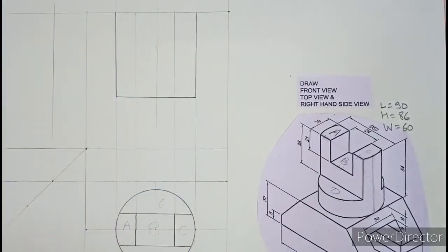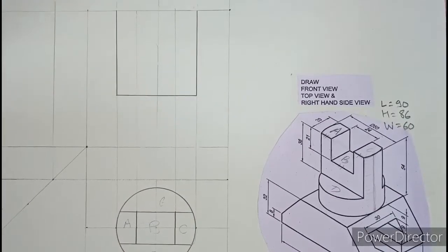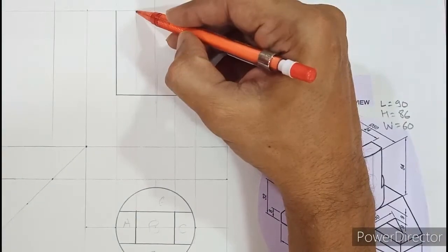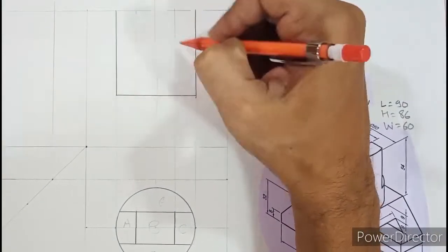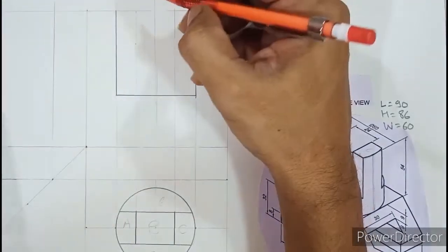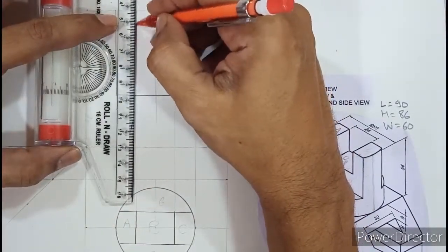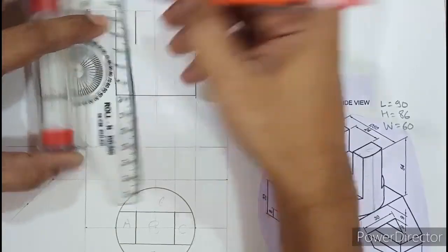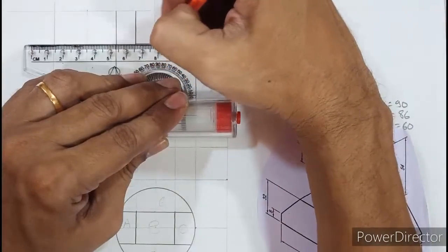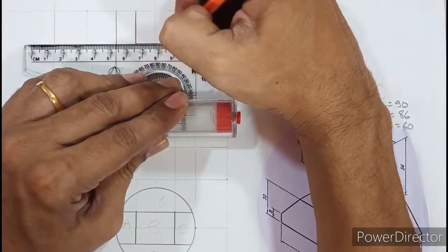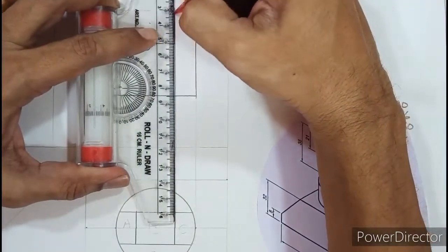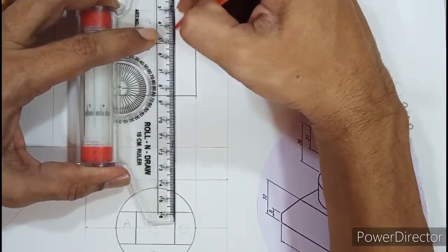Okay, now after this projection is done, we can come down by 21 from this point and draw the slot. So let us mark 21 millimeter. Okay, so from here we will darken this 21. We'll come down. So see, by mistake instead of 21 you might mark 12. So there are many drafting errors possible. You should be careful while marking each and every point.